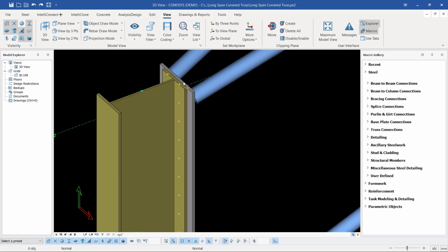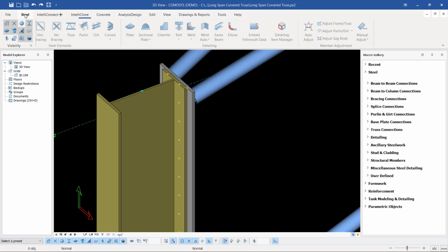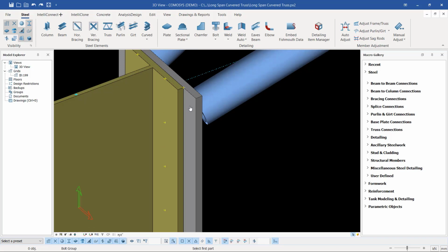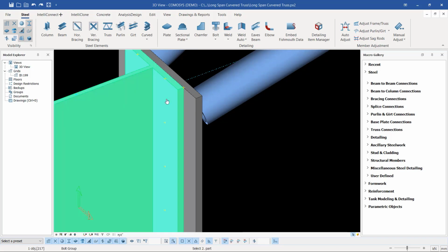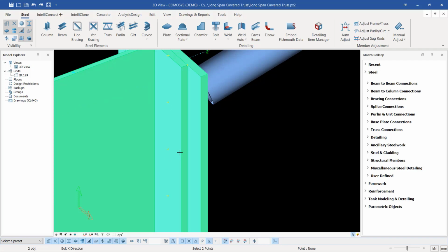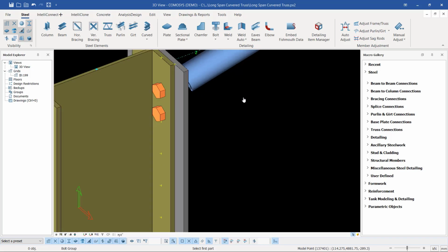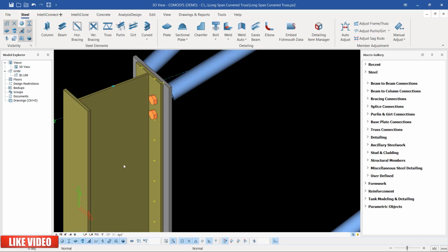Once I've placed it there, I'll go back to the tool for bolt creation and invoke that command. So I'll come back to steel here and pick on the bolt. Just click on the bolt and pick the parts you want to bolt together, not to weld. I'll pick the column and end plate here. Then I right click to make the command active. Now I zoom closer to the points I had created before, then I snap on that spot and snap on this particular spot. So you can see our bolts have been created. The reason why our approach was being rejected is because our XYZ plane was in the wrong place.